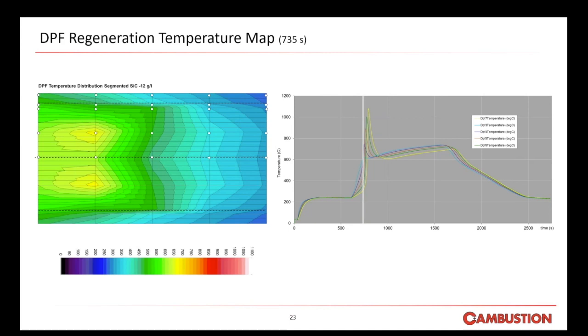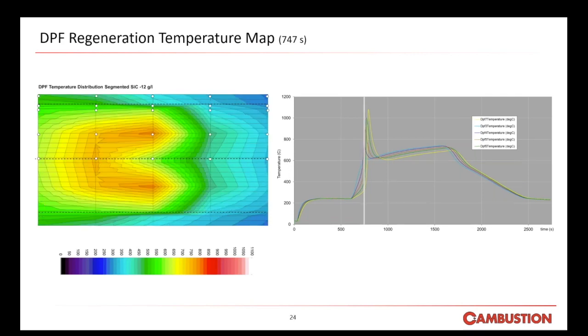Oxidation is beginning now. We can see from the chart here that the sort of yellow patches where it's reaching 650 degrees. So oxidation will be kicking off at the inlet. The heat release from this oxidation is causing temperature to rise throughout the first part of the filter. Most of the filter is not yet hot enough for oxidation to occur though. A wave of oxidation increasingly rapidly moves through the filter. If we look for the white line here, we can see spikes beginning to occur.